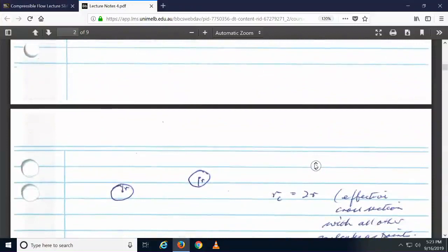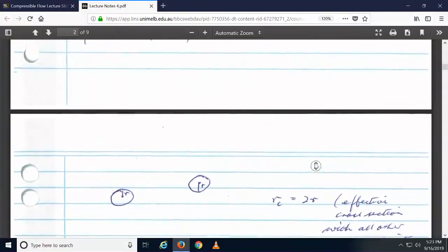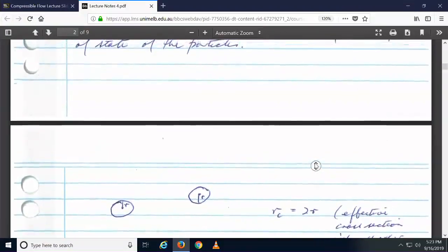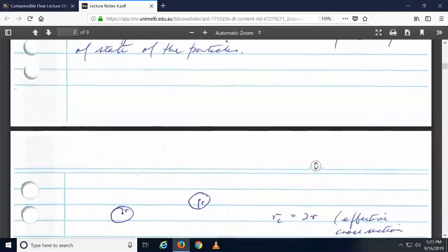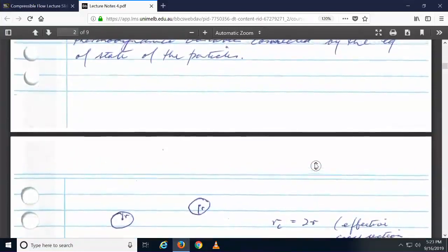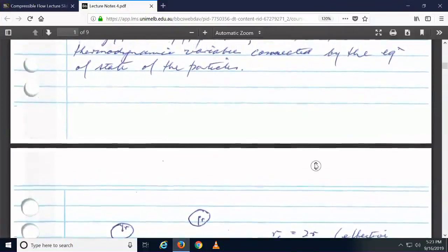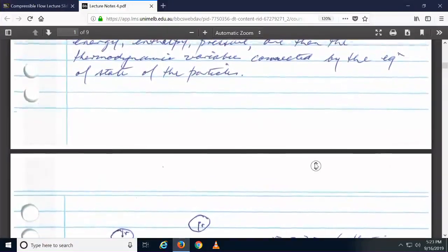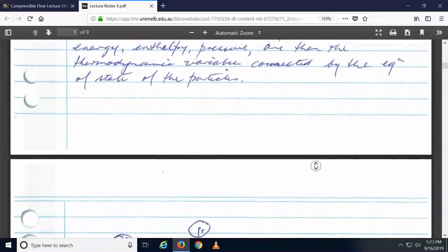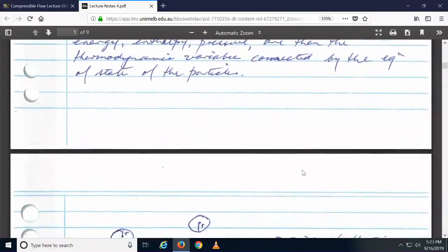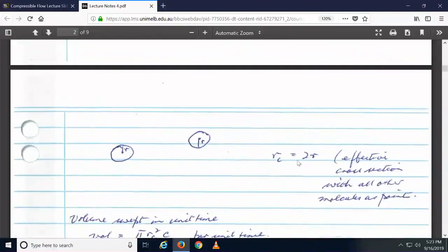So you're saying essentially that the fluid remains in thermodynamic equilibrium, and you're going to be in great trouble if you're doing hypersonics, and the flow time is comparable with collisions, because then you won't be able to use thermodynamics in the way that we are going to use it. All right, so now let's make some estimates. So how do you do it?